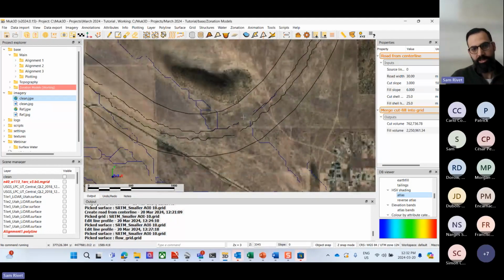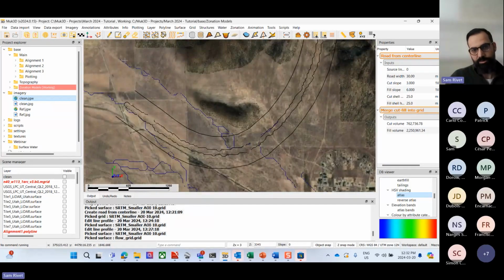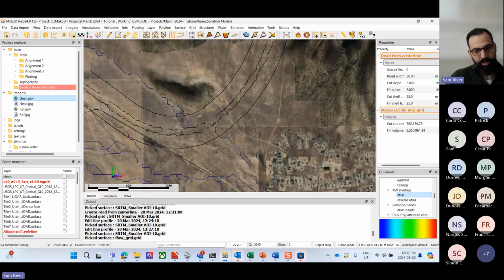Okay, now I'm looking at this one. This one definitely seems like a problem. The water seems to come from the northwest. It's going southeast, given the grading. It's crossing into the corridor. It's contacting the road. It's accumulating by the road, and it's going through the road. Okay, I can't really rationalize not doing something here.